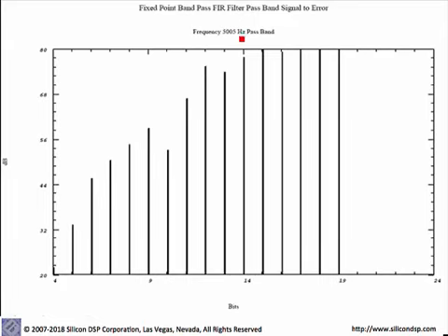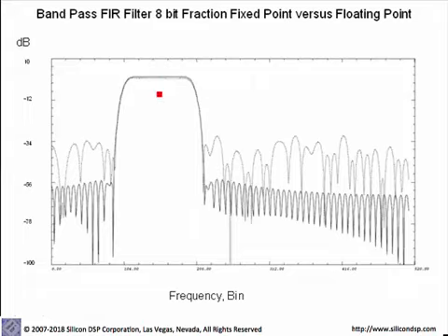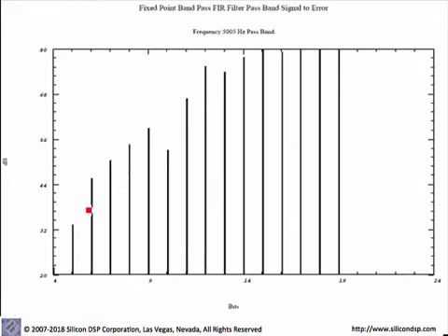If we look at the frequency response, the 5000 Hertz is in this region here. We see again that as we increase the number of bits for the fractional part, keeping the word length at, for example, 16 bits, or in this case actually the word length is a larger 32 bits, we can improve the performance as we add more and more bits for the fractional part, and of course beyond a certain point we get no more gain.